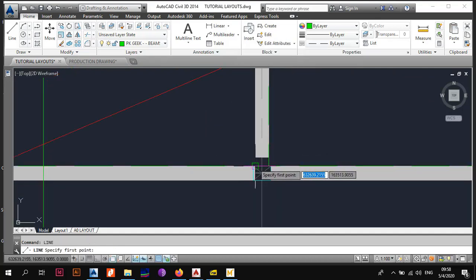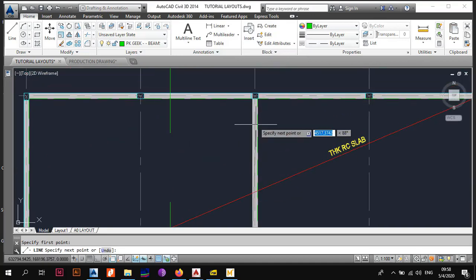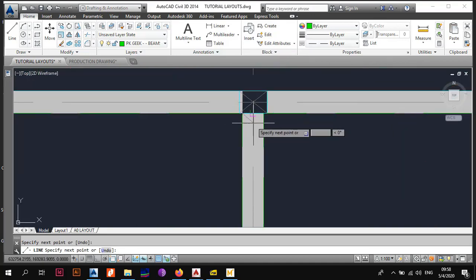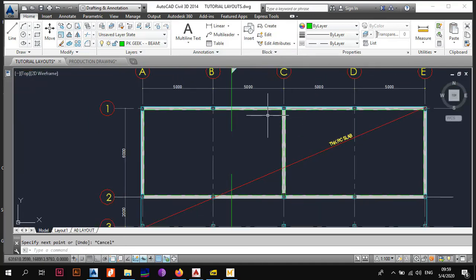we have a framed structure, because what we want is a framed structure. We don't want our slab being supported on the walls. We want beams to carry our slab, so that in case they want to remove the walls and just remain with partitions or anything, even if the client changes that they don't want 230 load bearing walls anymore, the structure is still integral. So sometimes you might find that you want to remove the wall that's in the middle and just have one large room.